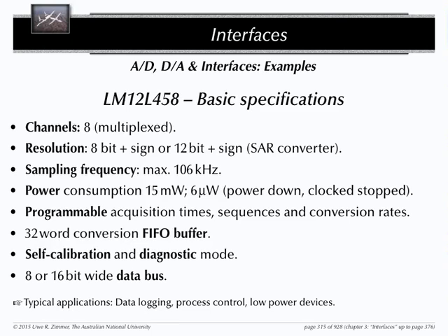You can choose the resolution of the thing, you can choose the sampling frequency, power consumption, 15 milliwatts, not particularly low, but also not particularly high. It has a power down mode, like most of these devices have, and it's important to indicate what the power down mode power consumption is. Why do these things have a power down mode?